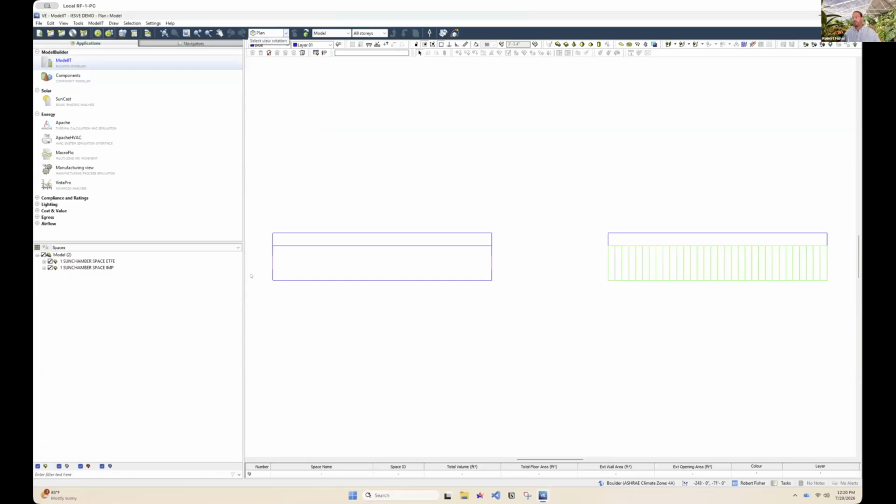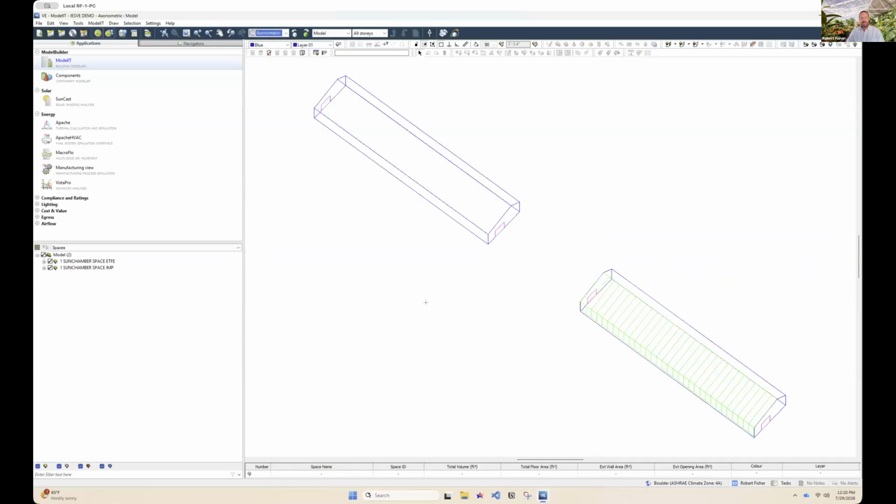Coming into it, it doesn't look all that special in reality. It's what you get out of it that's special. So these are two exact same size buildings. This one here is a fully empty building that's insulated metal panels, 3 inches all the way around everything. And this is one of our standard greenhouses that we utilize, which has IMPs on the back, but all of this glazing up here is ETFE.